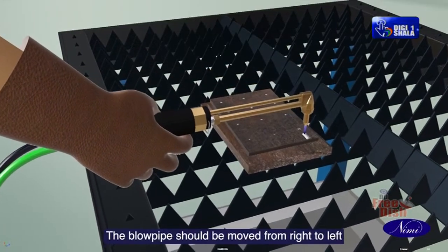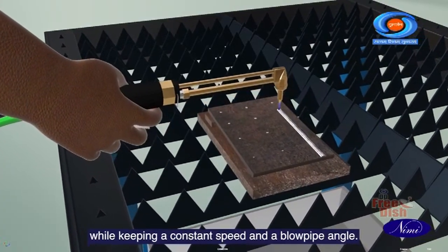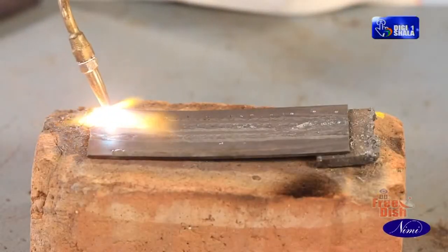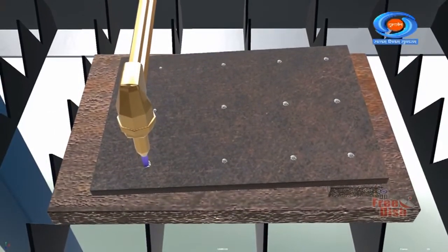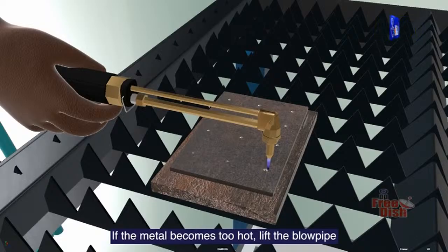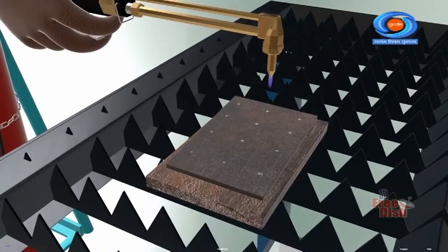The blowpipe should be moved from right to left while keeping a constant speed and a blowpipe angle. Keep the molten pool on the punch line. Avoid excessive concentration of heat at any point. If the metal becomes too hot, lift the blowpipe momentarily away from the molten pool.